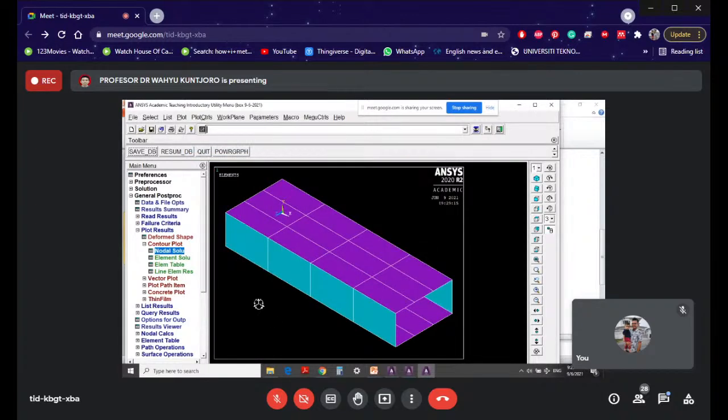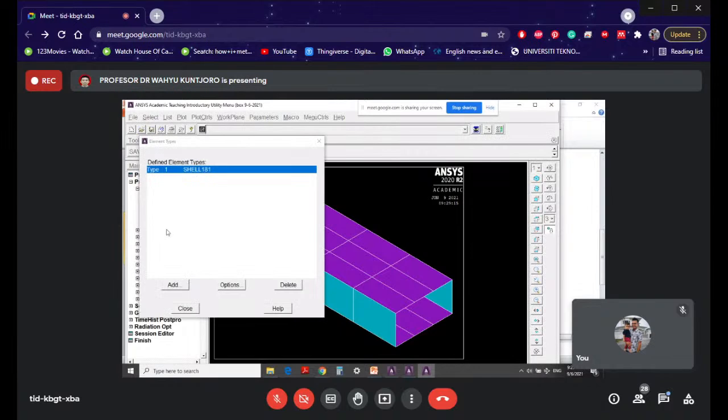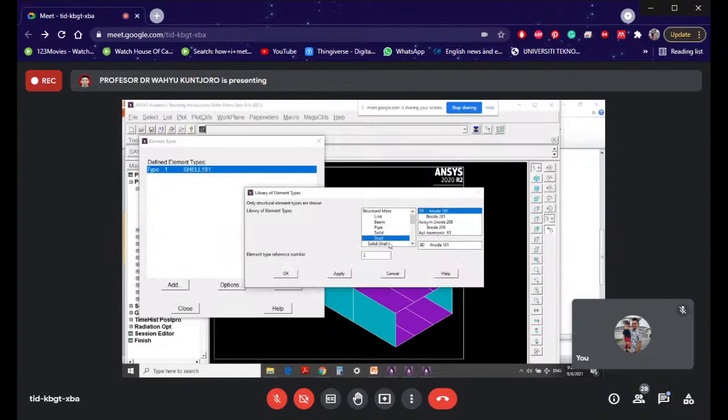Okay. So now we are going to create first our element. You go back to pre-processing, and then you need to create a beam element type. We have a shell, so we add one more. We go to beam, 2 node beam, and then I click OK.